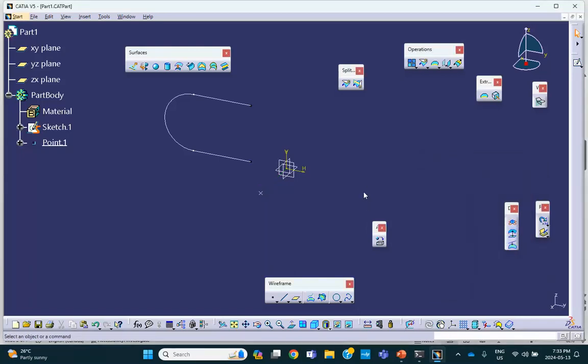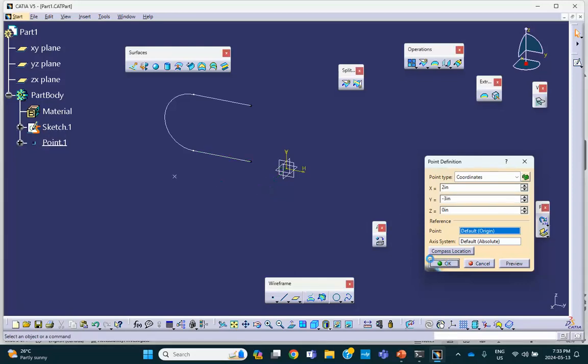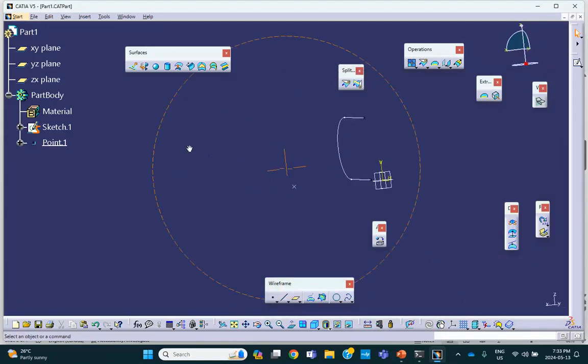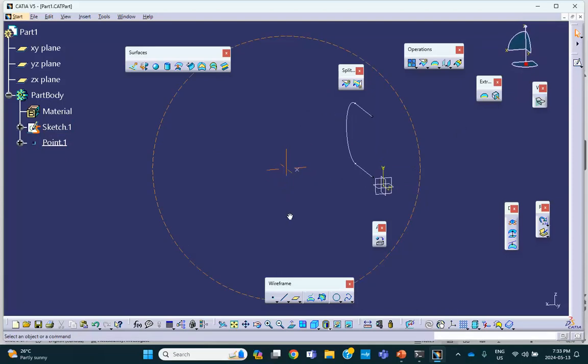Okay, good. Let me also move this thing a little bit to the back, although this probably would be okay. So -3. I don't think that's necessary, but that's fine. I'm gonna find there. So I created a point which is not on that line because the orientation point cannot be on the curve itself or on the continuation of the curve. So what I did is I actually made it away from the curve by some distance.